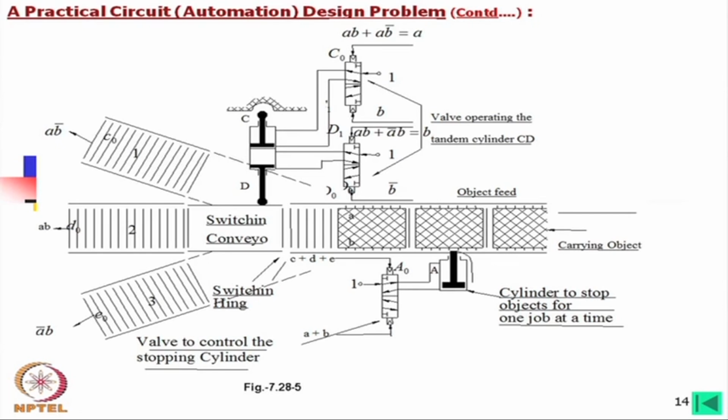And again they should be recognized as, if this is the first one, then it should go to the first conveyor. If this is the second type, then it should go to the second conveyor, and if it is the third type, then it is the third conveyor, like this. So, what is done basically, when the object is coming, first of all we must stop it, and then we should recognize it, what it is, type recognition. So, definitely there should be a sensor which will recognize what object it is.